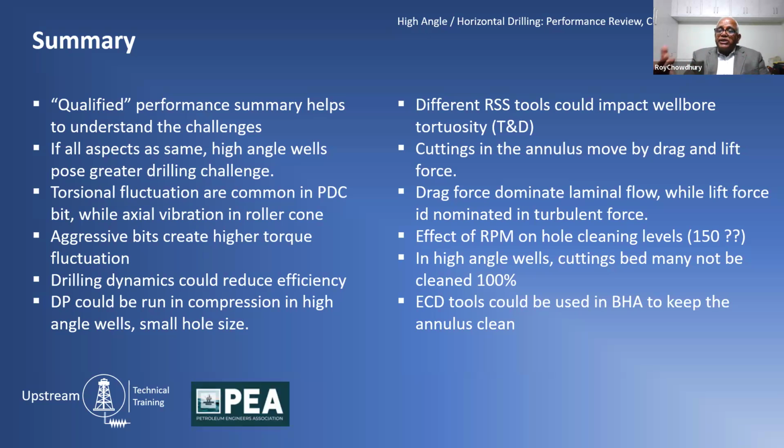There are times that drill bit engineers often use mixed cutters. In some specific areas, like the gauge, they will use impact resistant cutters, and on the face of the bit they might use wear resistant ones, because the position of the cutter in the PDC bit dictates the work rate.